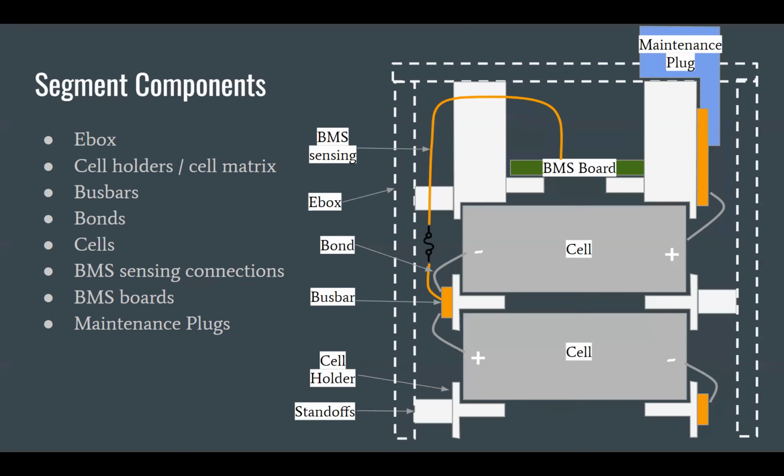And the idea is that the maintenance plug is a toolless plug that you with your hand could go in, grab, and use to disconnect the battery pack. You have to actually be able to use the maintenance plug to disconnect both poles of a battery separately. So you can't just have a cable that sticks out and plugs into the next one. You have to have two fully separate plugs that you can completely unplug and take out. So cool. And the big idea though, I emphasize with the maintenance plugs, it's not anything special. It's really just like a connector that's able to handle really high currents for our battery. It doesn't actually even do any data transmission.